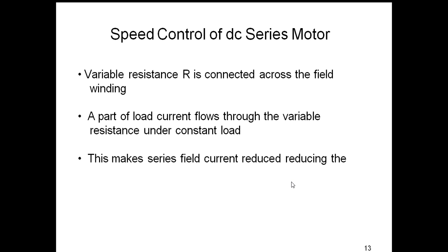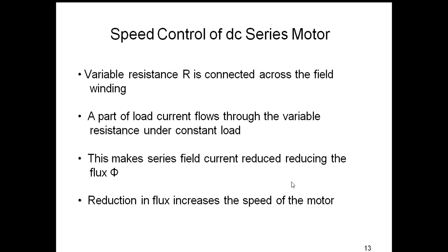This makes the series field current reduced, reducing the flux phi. When the flux gets reduced, the speed automatically gets increased. Reduction in the flux increases the speed of the motor.